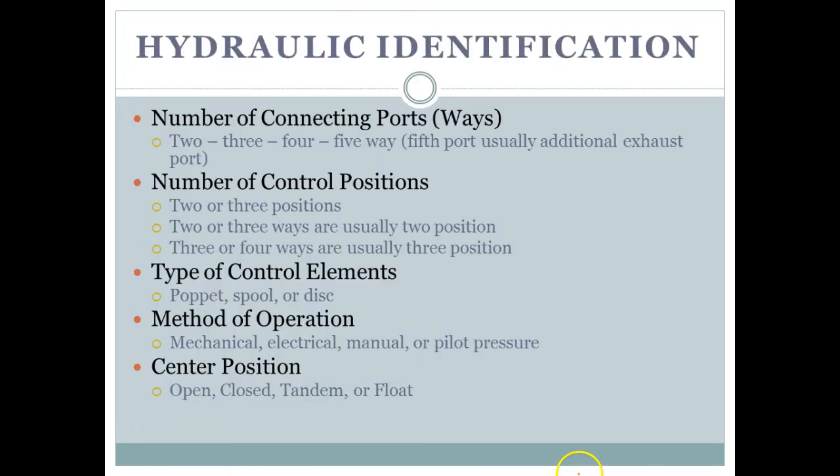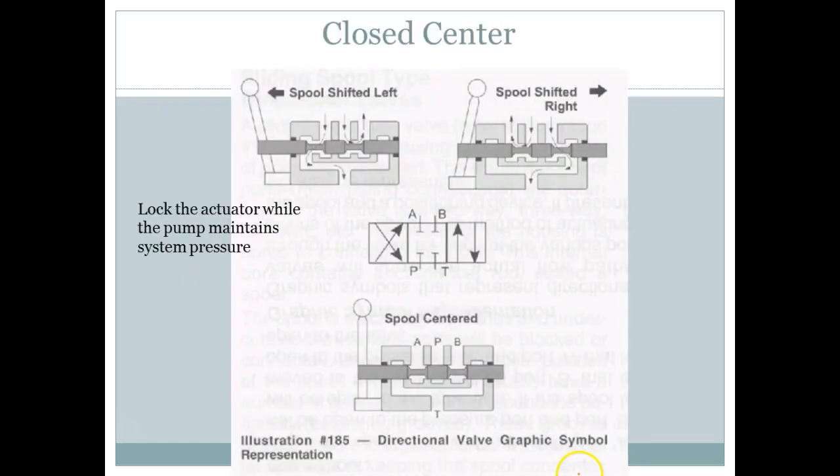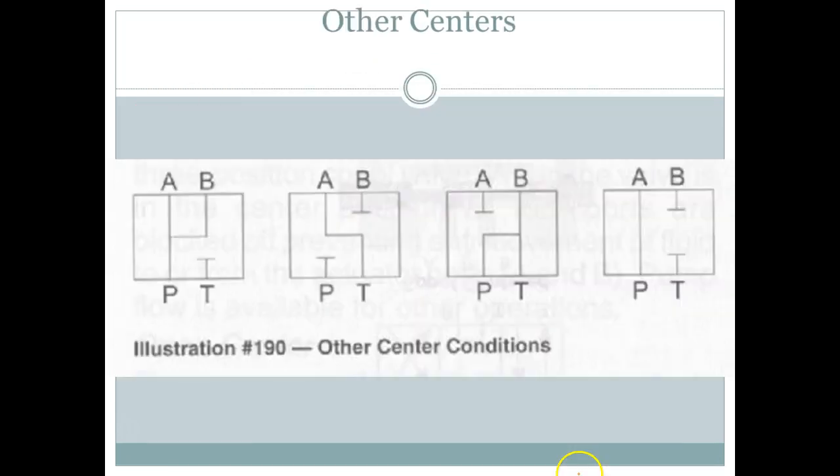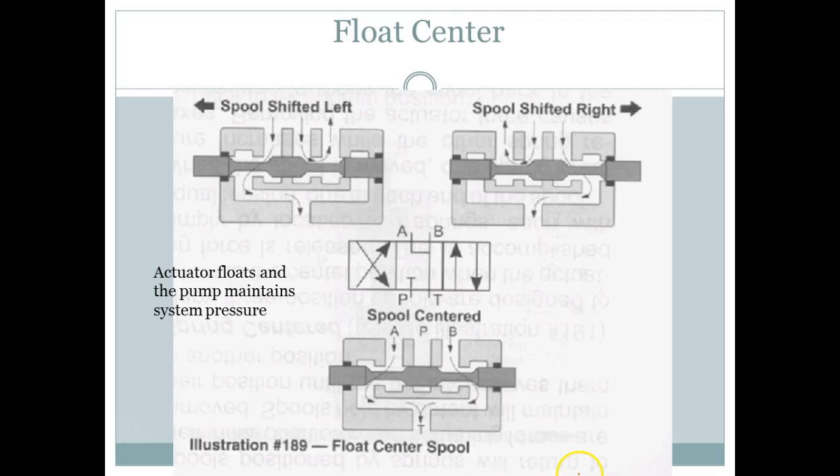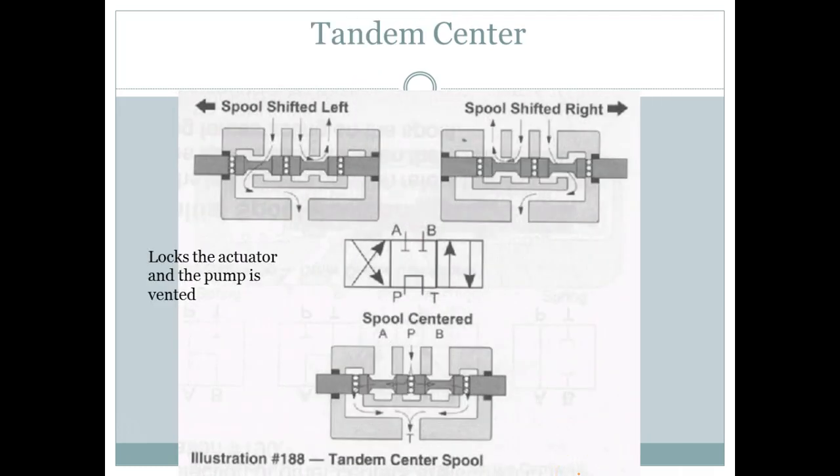Question. Do we have a choice? I mean, do we use any kind of liquid that doesn't compress for hydraulics? Sure. There's a system that runs water. Normally, if they run water, they'll put a lubricant in it, so you'll see they'll have white in them. So there are water systems out there.